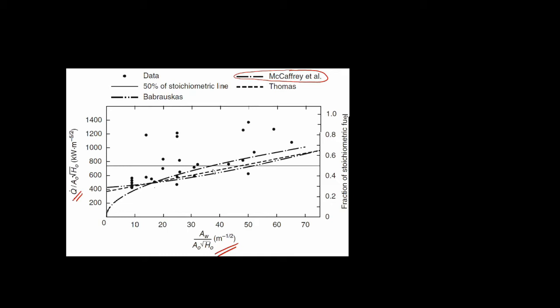Safety factors typically used in engineering are 1.5. I know for egress requirements, there's actually a code-driven requirement for 1.5 for evacuation times, travel distances, things like that. As you can see in this example, having a safety factor of 2 would actually be beneficial. So you have to really consider where the data came from in creating these models and just how unpredictable fire dynamics is. So keep that in mind as we go through, and if you ever try to evaluate a flashover heat rate, you need to factor in a safety factor there.